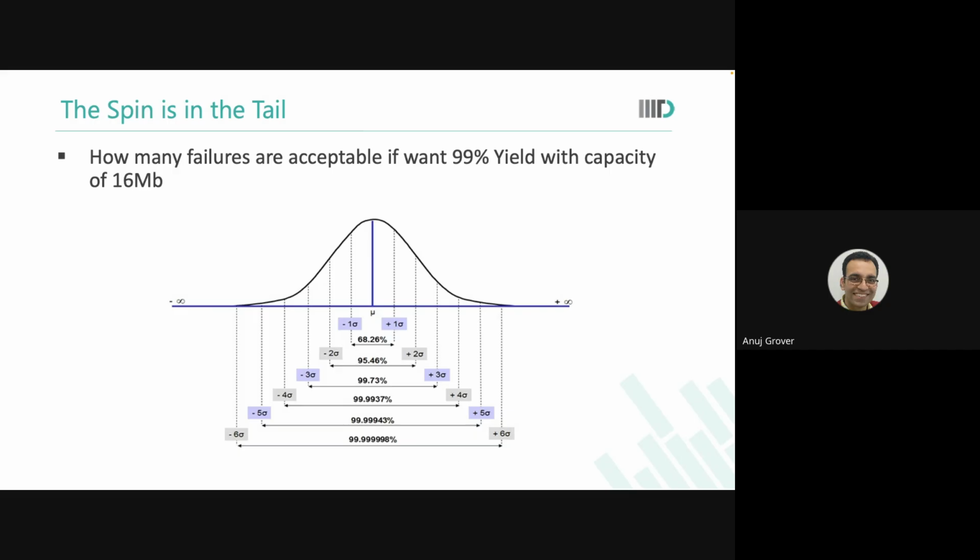But sigma, depending on how big your circuit is or which technology we are talking about, might stabilize at 100, 200, or 500 simulations. Whether you run 500, 1000, 4000, or 10,000, you will realize that the sigma value changes within 1% of it. So it's a law of diminishing returns. And once you arrive at that stable value of sigma, that is the number of simulations you have to launch to qualify your design.